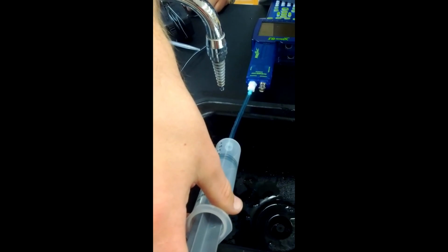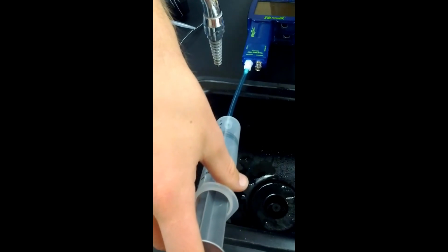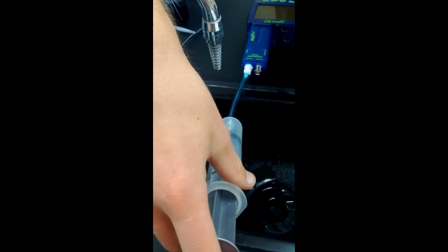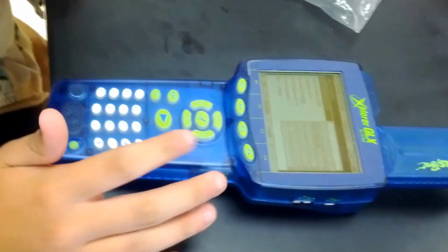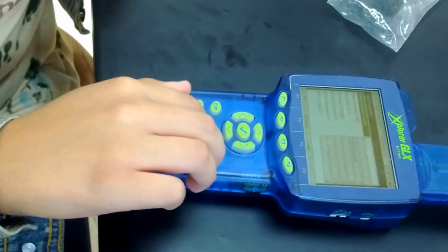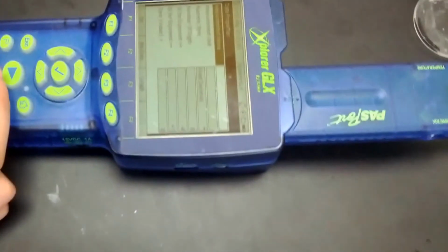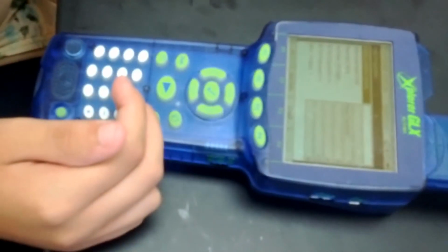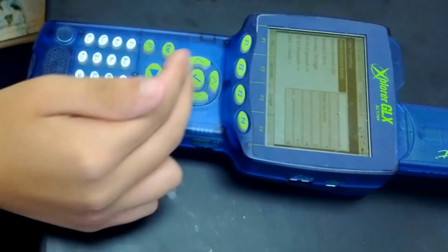And then we're going to align the quick release connector onto one end of the plastic tubing. In continuation, we go from the home screen, which is this little house button right here. Then we go to the sensor button, which is F4. Then we go to F1. And from here, you get this data point. And then you set this to manual mode by pressing F1, and then you press it to manual.